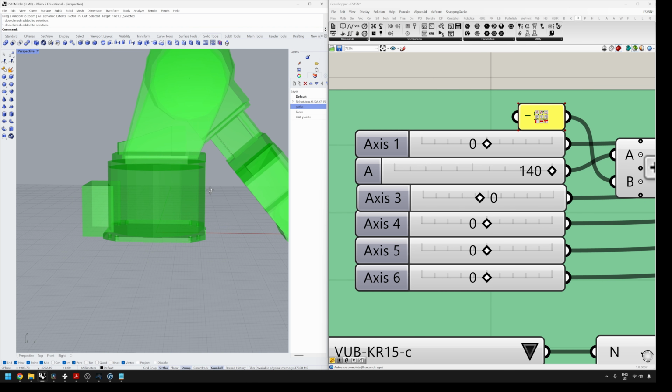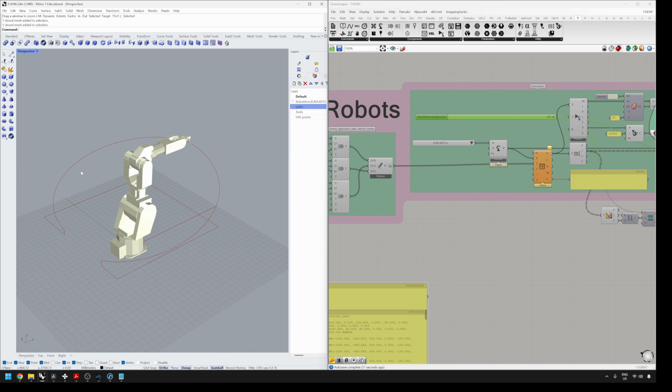The central question is whether these 3 results are actually consistent once the different joint signs, axis directions, and zero position offsets used by each plugin are taken into account, or whether one or more of the kinematics modules is fundamentally incompatible with the Kawasaki FS45N.